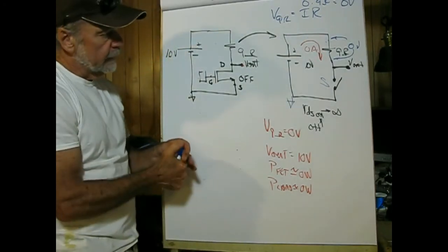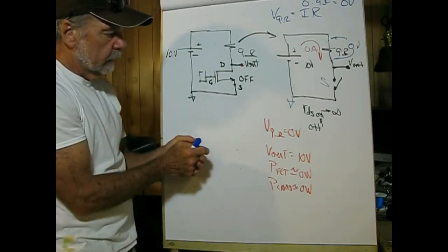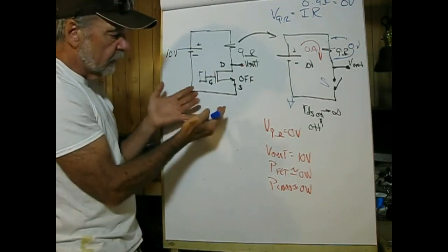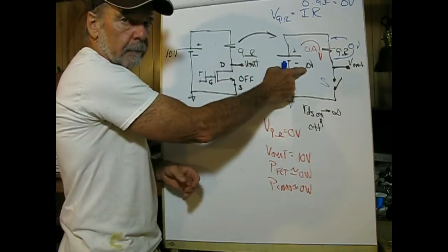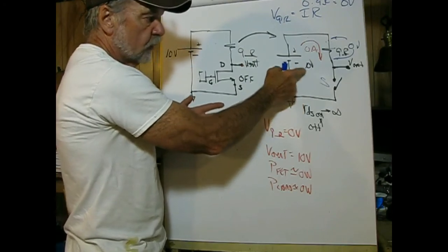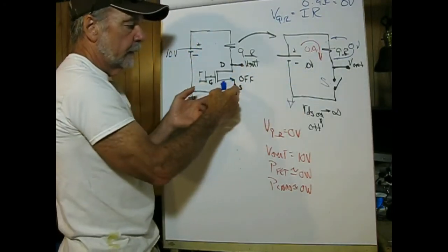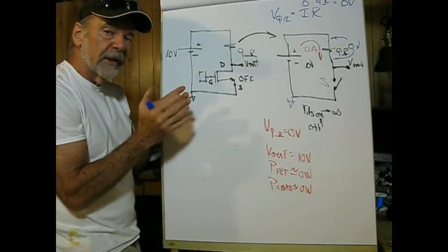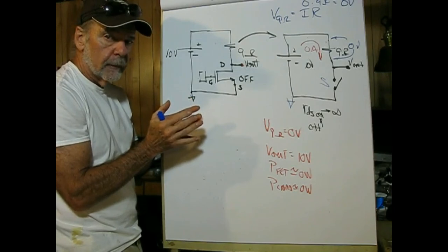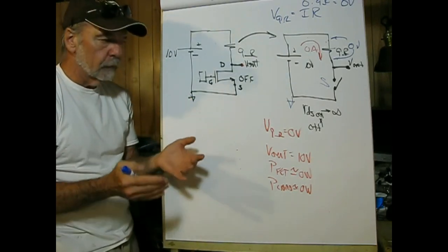So you can see we can take simple DC circuits and analyze rather complicated devices very easily by modeling them. This circuit doesn't exist per se, because this off here is very involved with some physics inside the transistor, but it looks like an open switch. So you handle it as you would a standard simple series DC circuit.